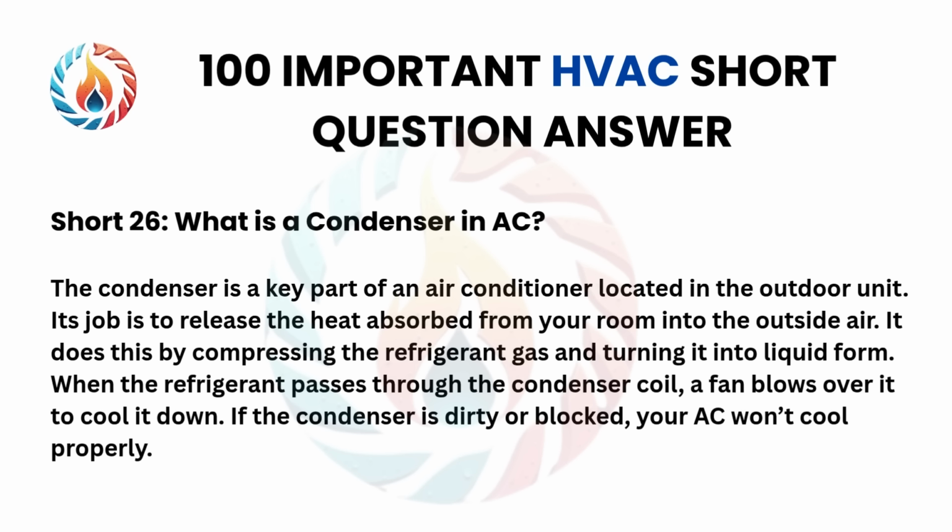When the refrigerant passes through the condenser coil, a fan blows over it to cool it down. If the condenser is dirty or blocked, your AC won't cool properly.